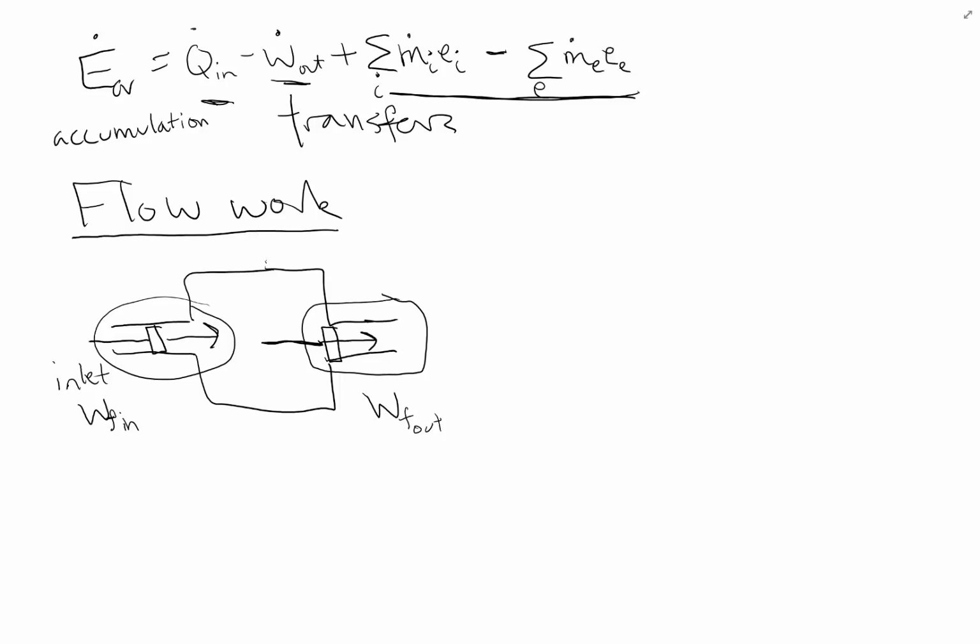The expression for flow work turns out to be fairly straightforward. Okay, so if you think of flow work or a rate of flow work, if you think back to chapter 1, chapter 2, force times velocity is going to be the rate of flow work because there's a piston here exerting a force. And as it exerts a force, it's moving through a velocity, or a rate at which the distance is moving. So the rate at which work is being done is force times the rate at which distance changes, so force times velocity. So we can break this down.